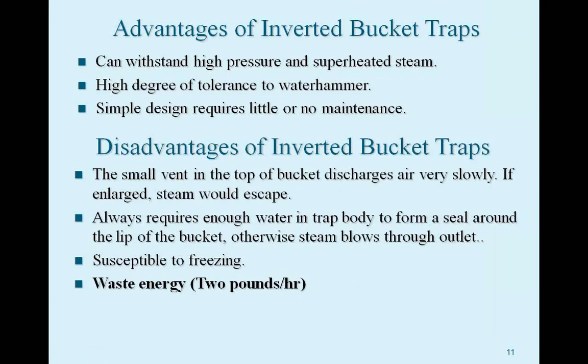Some advantages. Good for high pressure, decent for superheated steam. Not too bad for water hammer. You can see that in most cases they are not the inline type, but coming in from the side. So if there is water hammer, you get a lot of that absorbed within the pipe or before it actually gets to the bucket and hinge assemblies. Very simple design, very rugged, and very, very low in terms of maintenance also.